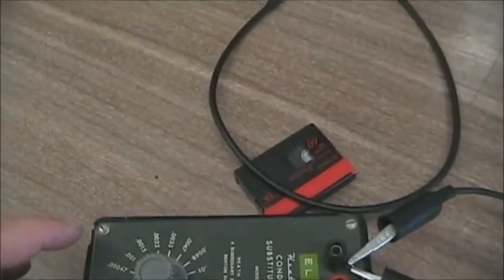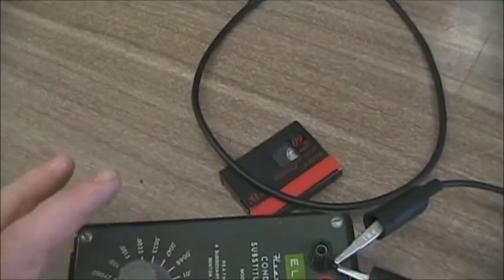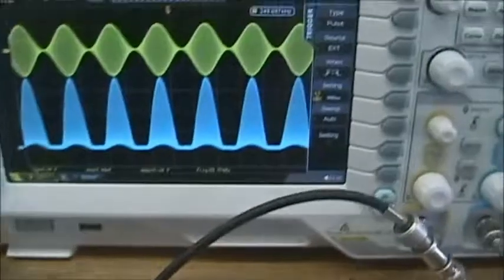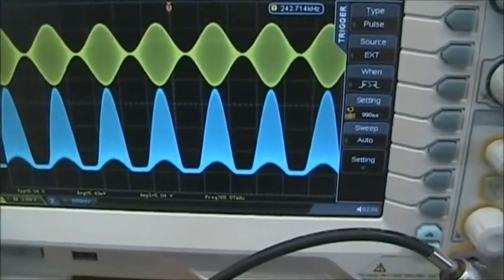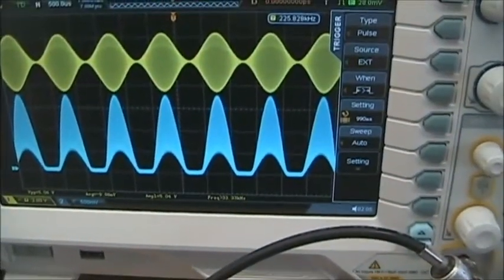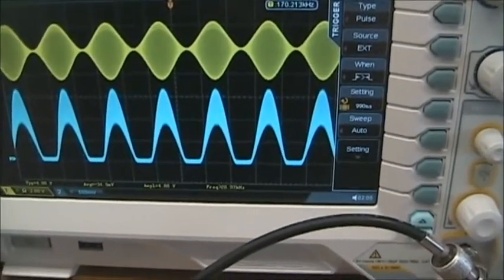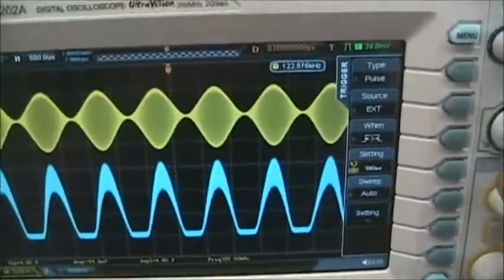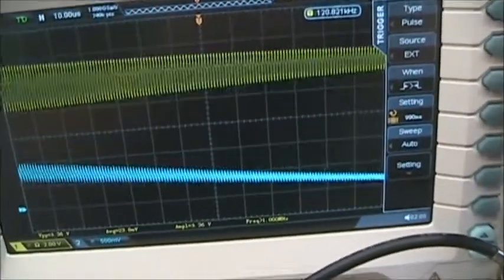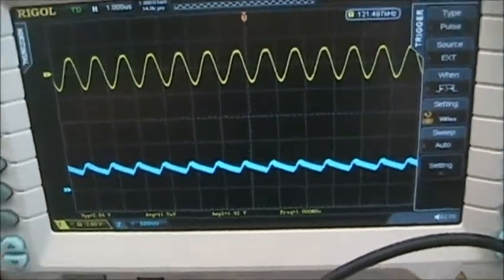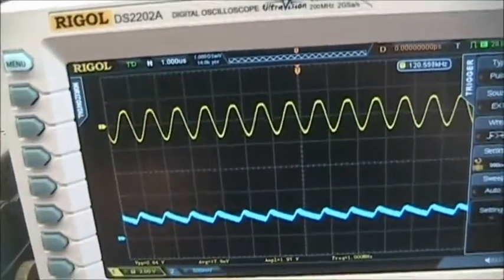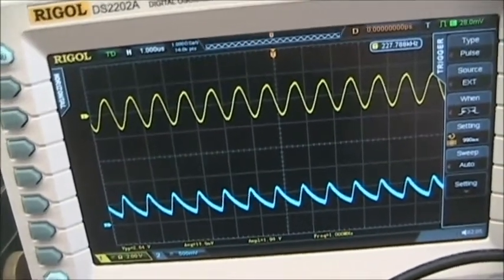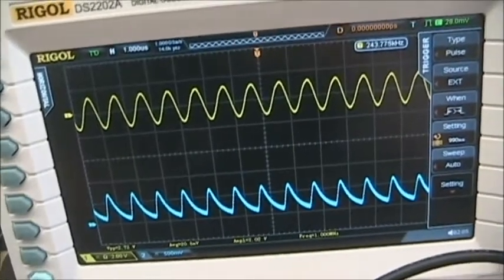So I'm going to increase from 100 picofarads all the way up towards 0.22 microfarads. As we adjust it, we start to see the filtering take effect on the demodulated signal. I'll zoom in here just so we can see what is happening, but you can see that now we get the classic capacitive discharge. I'll change the value to show that smaller capacitors give a shorter discharging time.